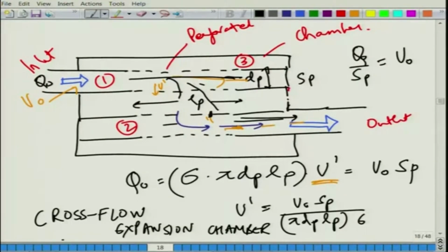The segmentation approach by Sullivan and Crocker, in Sullivan's papers from the late 60s or probably 70s, talked about considering gradually varying mean flow effects also. But in the analysis that we are doing, we consider the perforate impedance to be uniform throughout the duct.